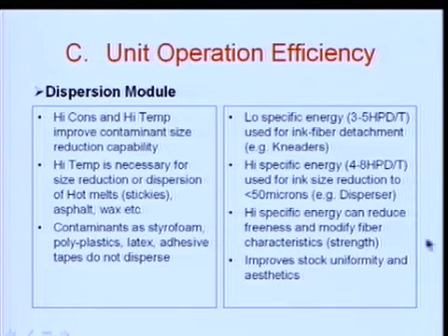High specific energy can reduce freeness and modify fiber characteristics. It can either improve the strength or decrease the strength. If the residence time is very high in dispersion, or you put a lot of energy in there and you get some cutting, it reduces the fiber strength and reduces the freeness. If you just do enough at a very high consistency, then you are not reducing the freeness by that much, and you can actually help improve fiber strength. And of course, both dispersion and kneading are basically mixing processes where you can mix chemicals if you want to, but it also mixes the whole stock and improves stock uniformity, homogeneity and aesthetics.